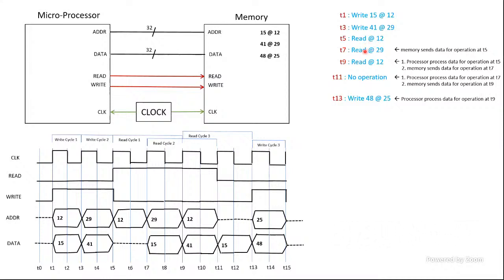Back-to-back read is also possible, but back-to-back read-write is not possible, simply because of this phenomenon. That's why we need to place a one cycle gap there. Just to make sure you know what I mean by the cycle: one positive edge to another positive edge is called one clock cycle. So back-to-back operation means in successive clock cycles, from one positive edge to another positive edge. That's called one complete clock cycle.